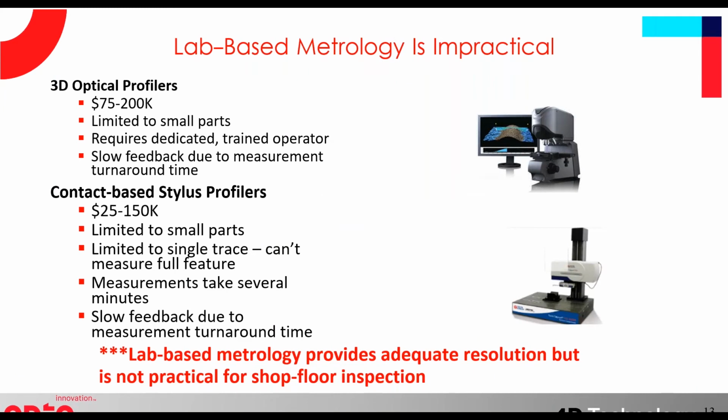Lab-based metrology typically has plenty of resolution, but it becomes impractical for most shop environments. The systems are very costly, they're limited to small parts, the operator typically needs a lot of training, and because metrology labs are typically very busy, it can be hours to days before a measurement is completed and results are known.